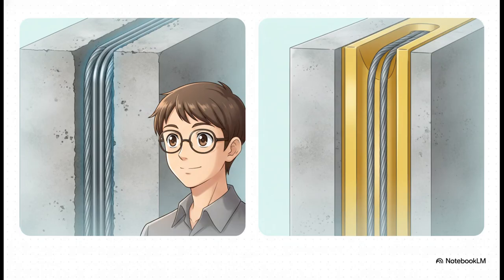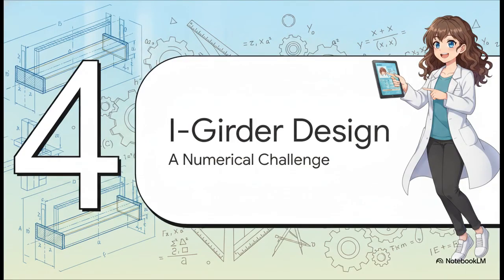On the flip side, unbonded tendons are free to move within a duct. Now, you see this in slabs sometimes, but it's not great for heavy bridge infrastructure. Because Indian bridges demand incredibly high durability, we focus almost exclusively on bonded grouted tendons. So Table 11 is going to be our best friend today. All right, Section 4, the I-girder design challenge.